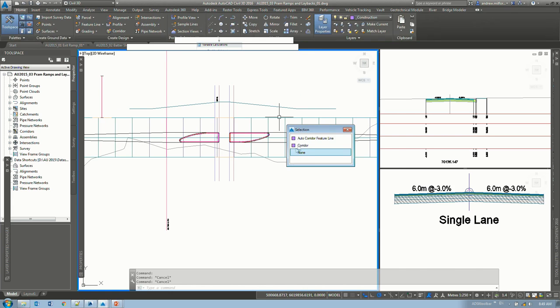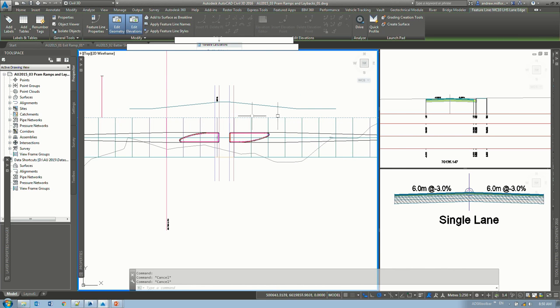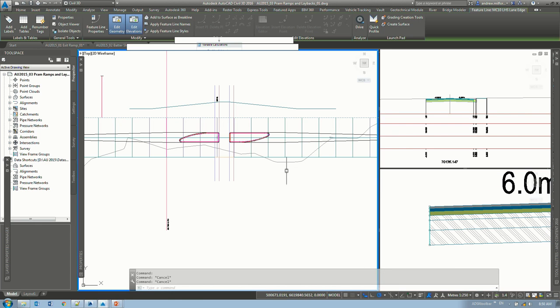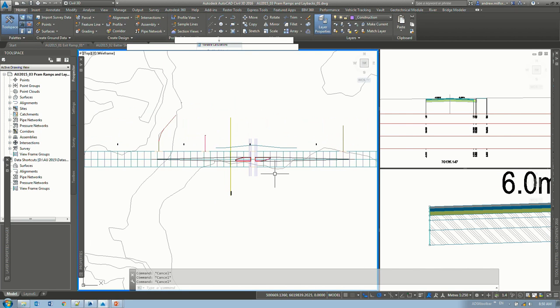In this case, I've already gone ahead and set up an automatic corridor feature line on this point down here. It's using the linked corridors. Once again, it just gives us that flexibility. If we decide to move our property access curb layback, we can just slide it along. We don't have to regenerate the mainline corridor as well as the others.